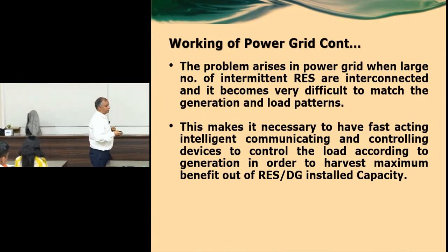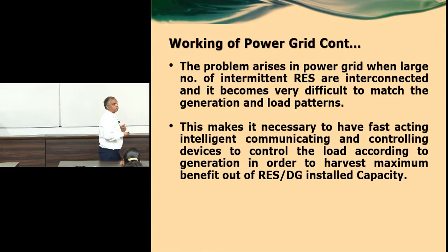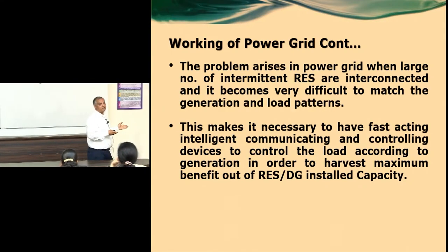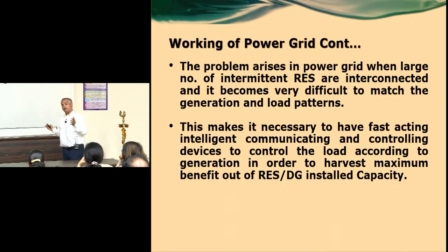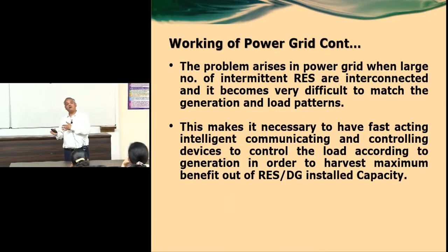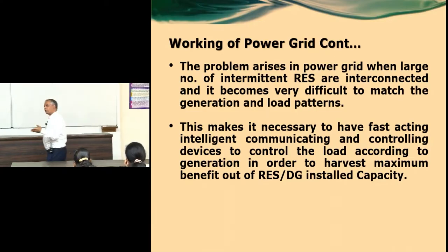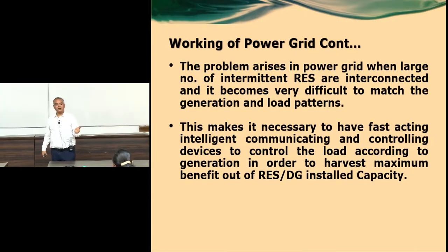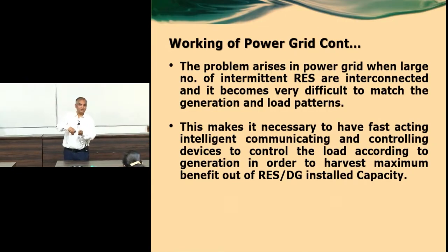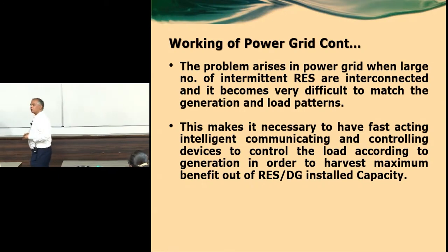Maybe in future tidal energy is also going to be harvested, so it is also situated away from the bulk load centers. So evacuating the power being generated at those faraway centers is again a big problem, because of the typical problem of the Ferranti effect. Under light load conditions, the receiving end voltage is higher than the sending end voltage. But what will happen if you are generating more at the receiving end? Then the voltage is again going to shoot up.